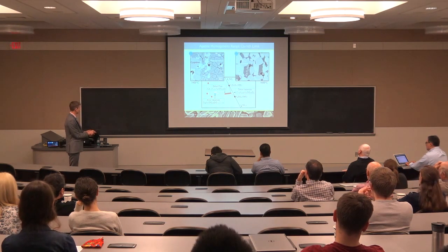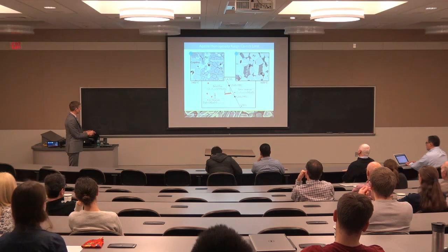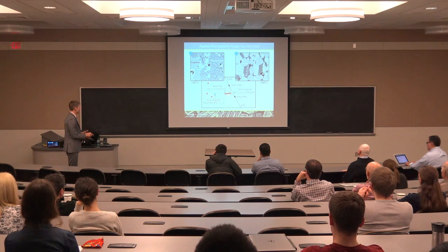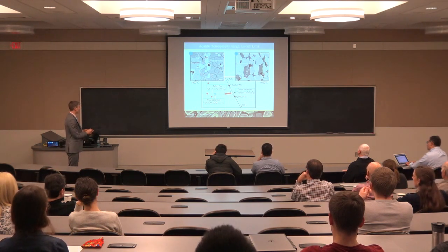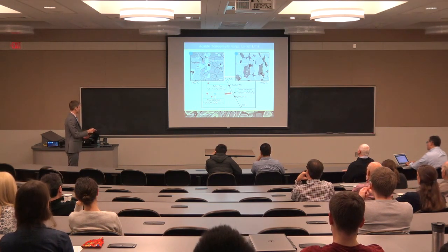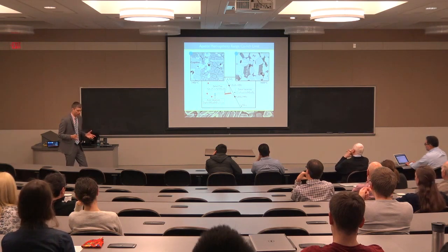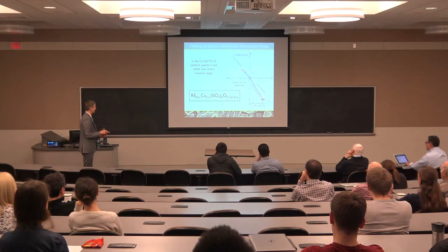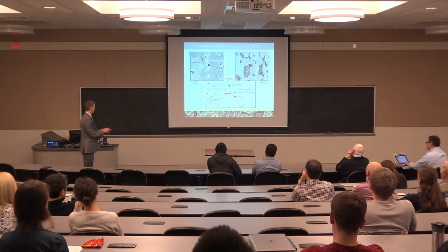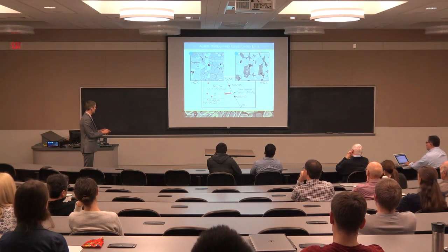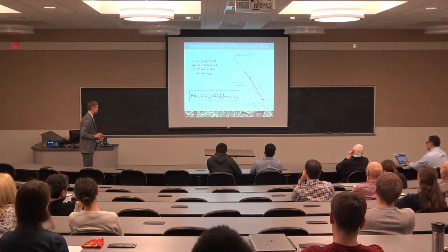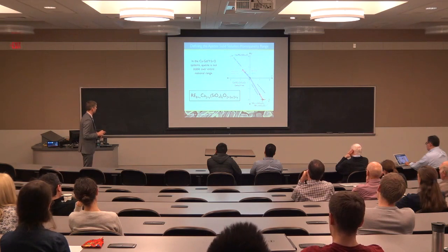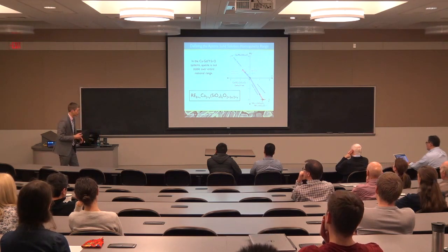We can then go in the other direction, prepare a composition out here that corresponds to what would be the calcium-rich or the anion vacancy stabilized form of apatite. Again, we don't get single-phase apatite, we get three-phase mixtures at both temperatures we were investigating in this case. And with that, we can then map out where the terminus would be here, and then map that back onto this schematic that shows more directly the influence of the different ionic defects that enable this range of compositions.